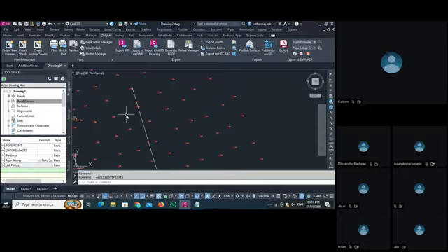Sometimes, if there is black cotton soil or clay type of soil, and they are passing their alignment there, and at that particular area they find the soil type as black cotton soil or whatever soil, and the particular soil report is not there, or the engineer wants the detail of this point, then what the engineer or draftsman does is decide that point as per the senior's description, and they provide that point to the surveyor team again, and the surveyor team marks that point with the help of DGPS or total station, whatever survey instrument they use, and that marked place is provided to the geotechnical team.